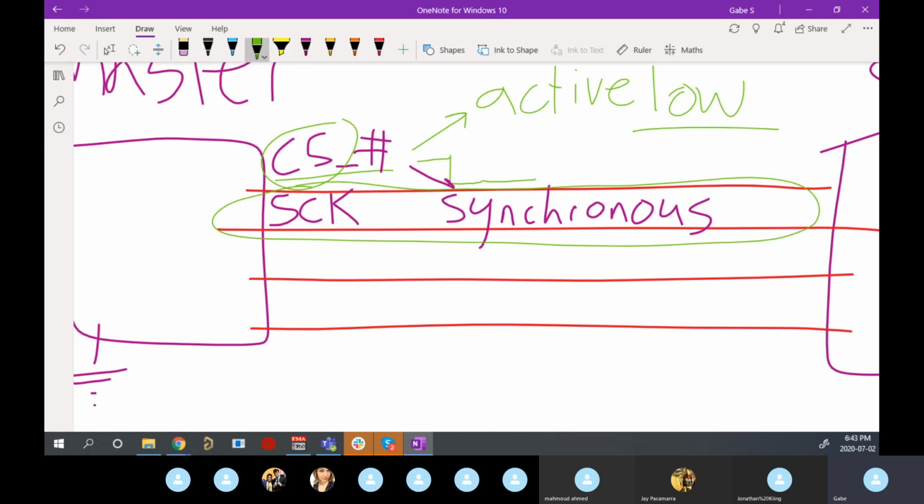And so it's really easy for the master just to decide which clock to send at what speed, and the slave will have access to that and can just read at whatever clock the master needs. You don't have to have a predefined agreement on what speed we're going to talk at, which is nice. Drawbacks, it adds another wire, right? So it's a pro and con.